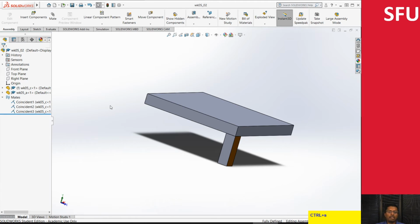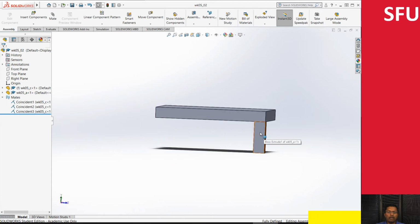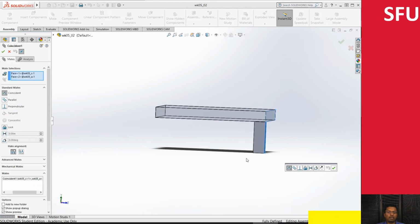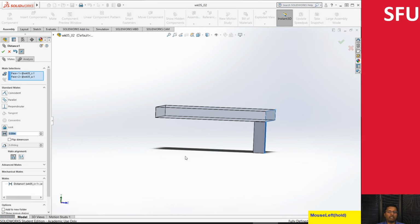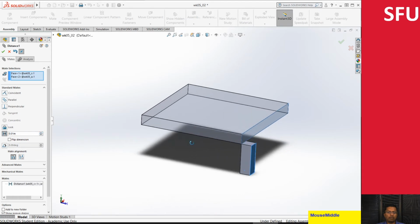As usual, we save our part. And suddenly, if I realize that maybe I wanted this leg to be offset inside a bit, what I can actually do is, if this menu is collapsed, I can click. Then as I move through, it tells me which constraints are highlighted. So I can select this constraint and then say edit feature. And instead of it being coincidental, I can actually make it parallel at a particular distance. I click on this distance feature and then increase it. So now it's come out.